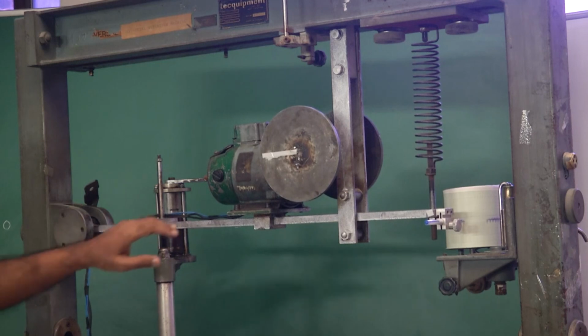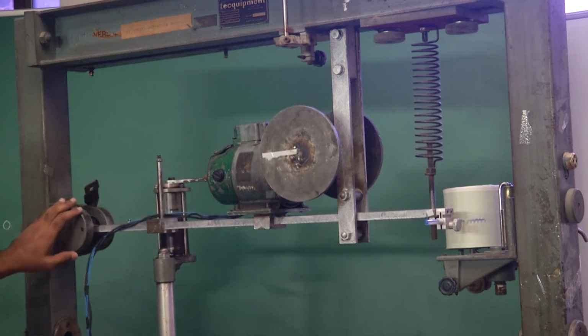This one could be friction damping, because there is a relative motion. Depending upon how lubricated it is, there would be either viscous damping or there could be Coulomb damping if there is metal to metal contact.